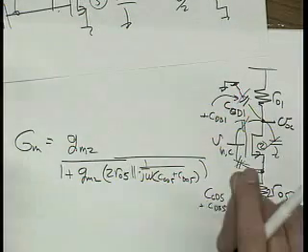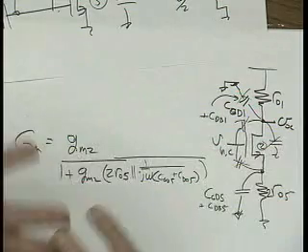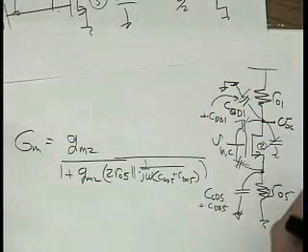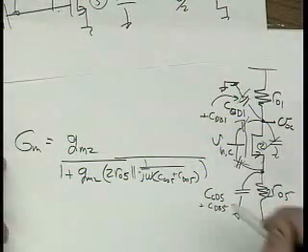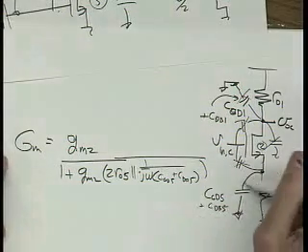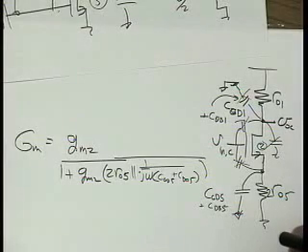So now what's going to happen to the common mode gain? Just intuitively, can you see what's going to happen with common mode gain as we go up in frequency with this circuit, if we worry about this capacitor primarily? Who can tell me? It's going to increase.